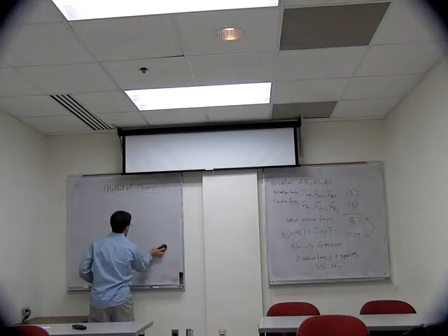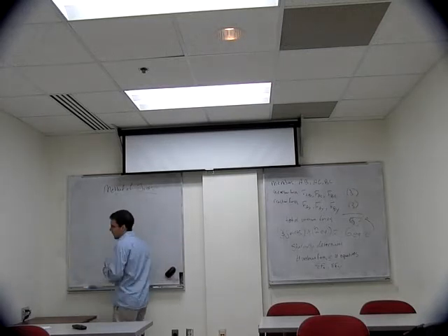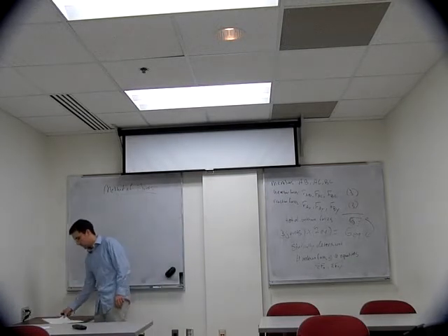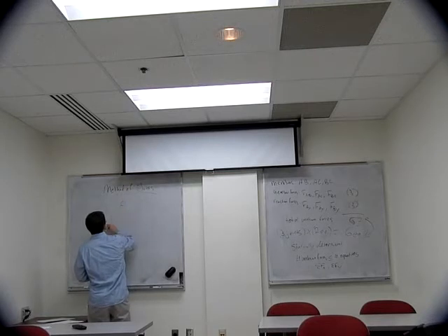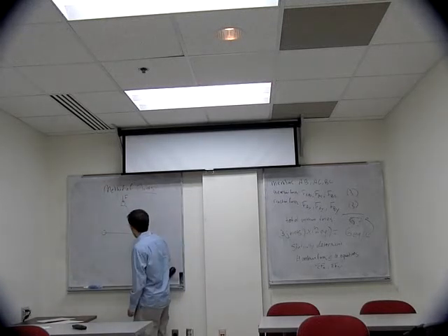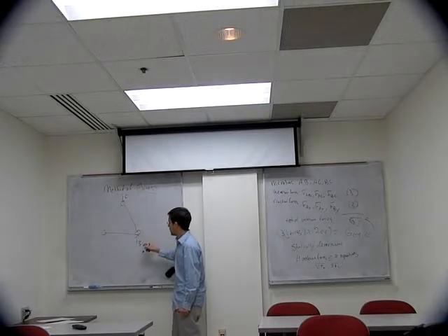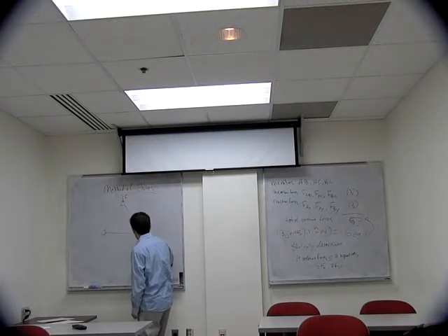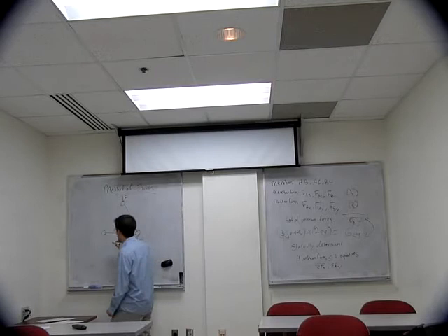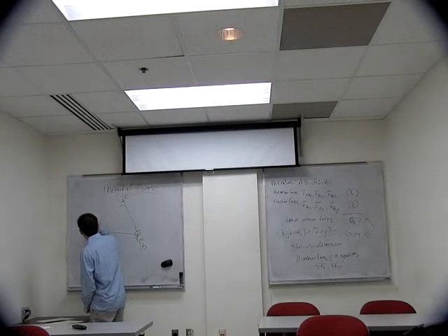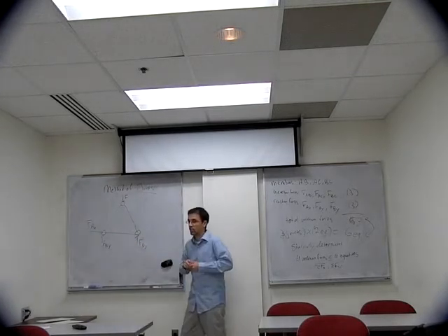So the first thing to do in the method of joints is to look at the system as a whole. So we'll look at only the external forces. So we'll draw the overall system again, looking at just the external forces. So the external forces are our applied force and our reaction forces. Remember at joint B, we have only the reaction force in the y direction, not in the x direction. But at joint A, we had a reaction force in x and y.